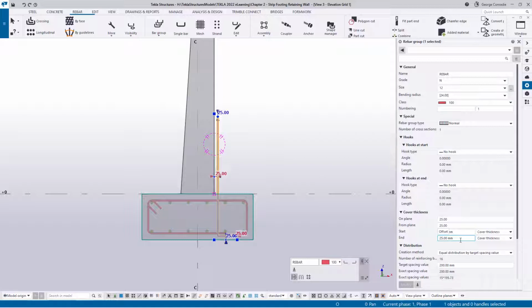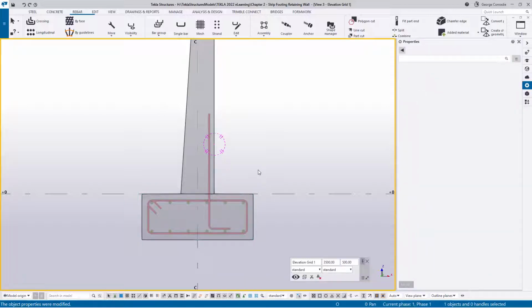So first thing is our start is a leg, and the leg is a 200. So it takes care of that. Our cover at the bottom is 98, and the cover on the side is minus 39, and that will take care of that. And then at the end over here, we know that we've got a 0 there to get the same bar length. So that pretty much wraps that up.